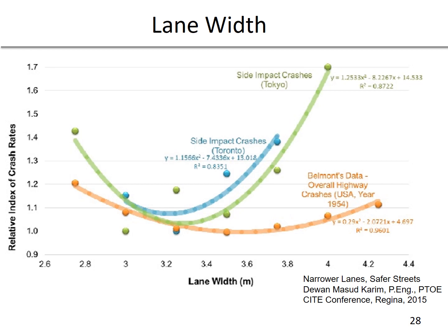But certainly, if lanes get too wide, you're going to induce higher speeds. If lanes are much too narrow, you're going to have vehicles that are too close together, particularly with heavier and larger vehicles. They're going to create too much friction there. So there is this kind of happy medium of lane widths that we should consider and think about when we're designing a roadway and choosing an appropriate lane width for that roadway.